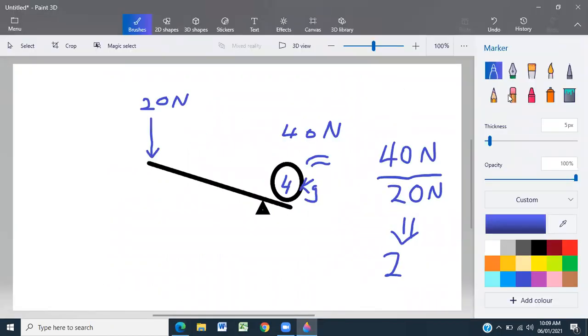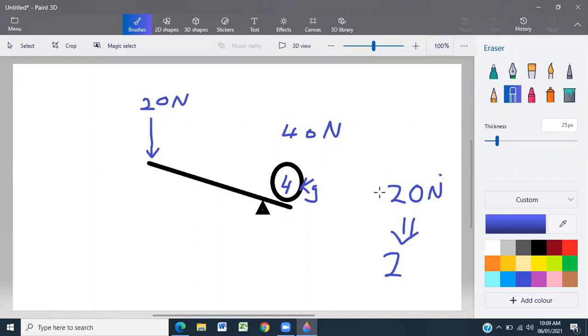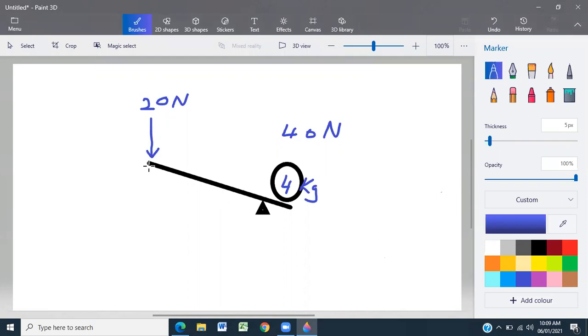Another important property of a system is the movement ratio, sometimes known as the velocity ratio. But thinking about it as a movement ratio is much simpler. It will help you understand it better. If you were to carry this lever all the way down, you would travel some distance, let's call it d1, and this end would travel some shorter distance, d2.